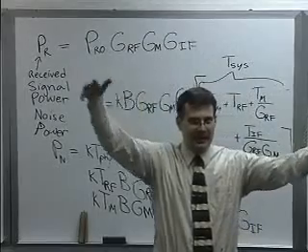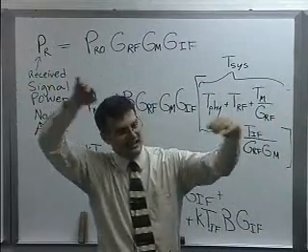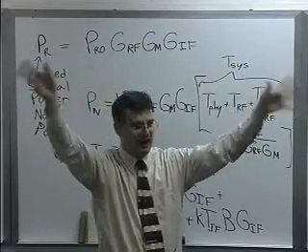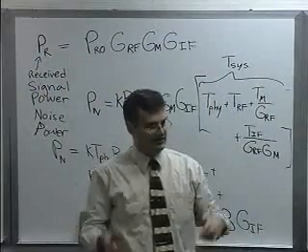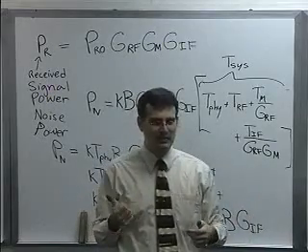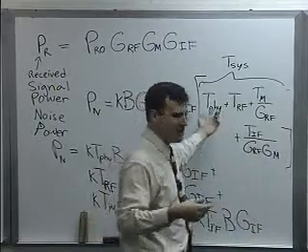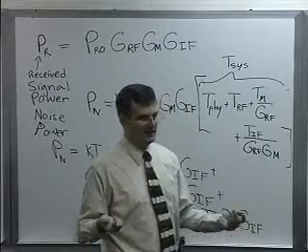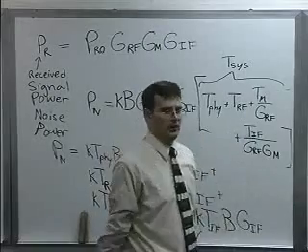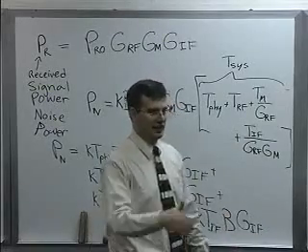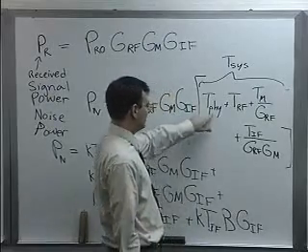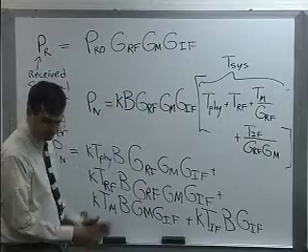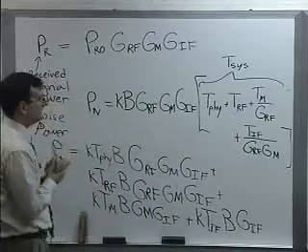If the side lobes are pointing off into space, and you kind of got to weight them spatially against the non-hot areas of space, and so forth. And so it winds up being kind of rules of thumb anyway for that number. You say, oh, you're operating on Earth, you're pointing to the sky with a fairly directional antenna, physical temperature of 120 kelvins. You know, you kind of read that off the book. But you're right to notice that that does not include the gain of the antenna. So yeah, this is your system temperature.